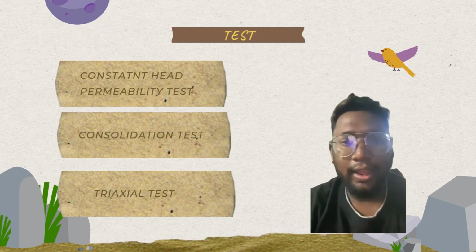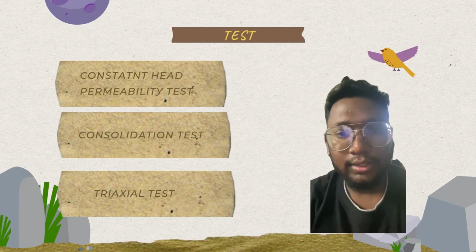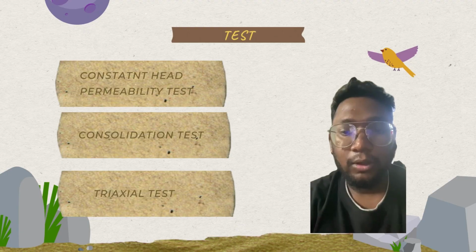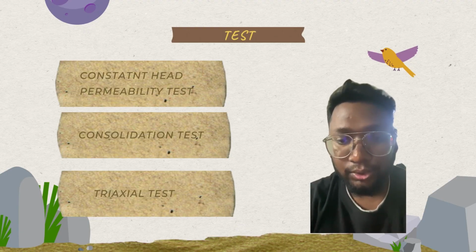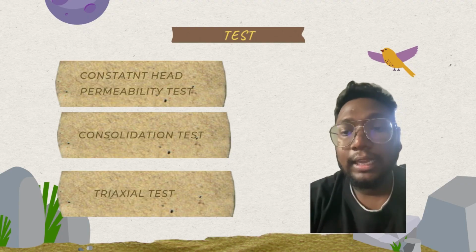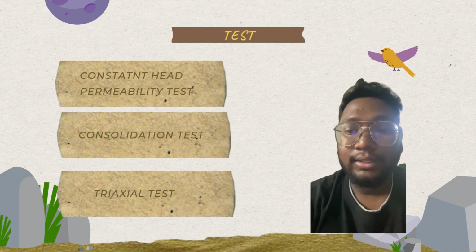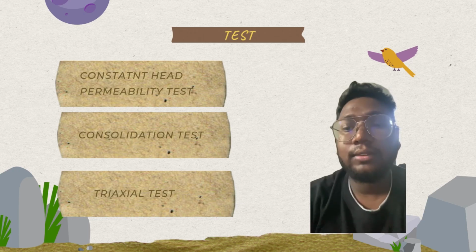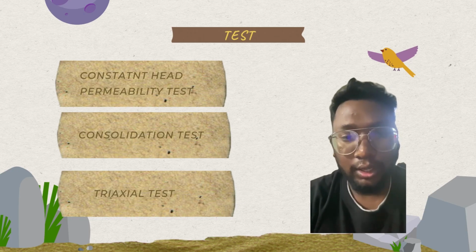Lastly, the triaxial test. The triaxial test is to measure the shear strength of the saturated soil under different loading and drainage conditions, and also to study how pore pressure affects the effective stress and strength. It is essential for slope stability, foundation, and earthwork design.